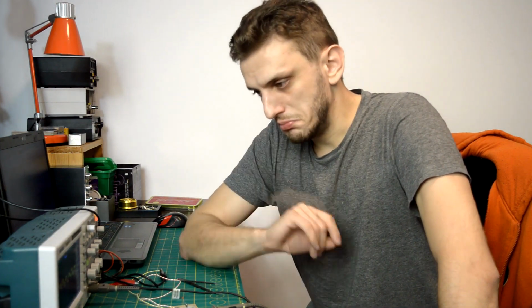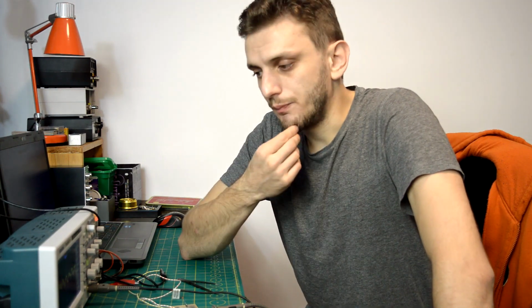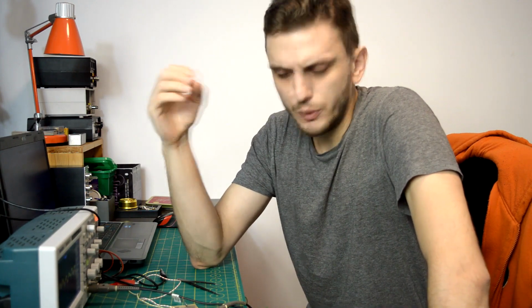Now as long as the noise that you're measuring has tens or hundreds of millivolts of amplitude, this way of measuring is completely fine. But most of the circuits we simulated today had noise in the order of tens or hundreds of microvolts. Now that is way below the noise floor of a cheap oscilloscope. And sometimes it's also below the noise floor of an expensive oscilloscope. Now, if only there was a way in which you could measure very small voltages without having to spend a fortune on test equipment.